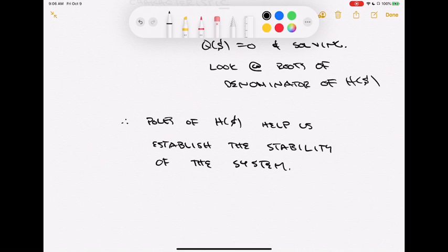You can tolerate unrepeated roots on the omega axis, right? That would be a marginally stable system, but if they got repeated, then it would become unstable. So all of those things are the same. We can just assess it using this system transfer function, this H(s). H(s) is one of the fundamental mechanisms for understanding an overall system, a linear time invariant continuous system's behavior.